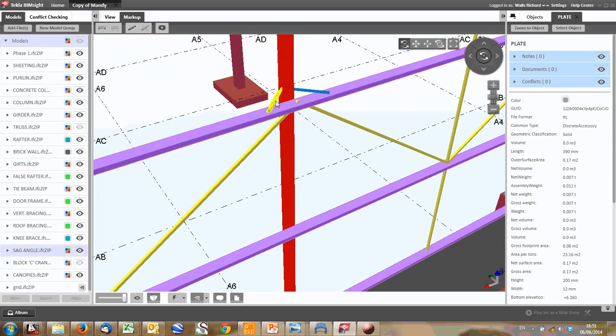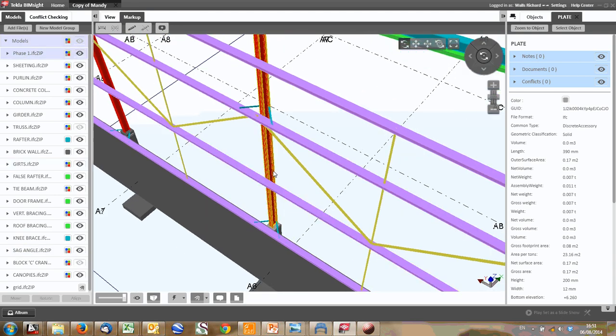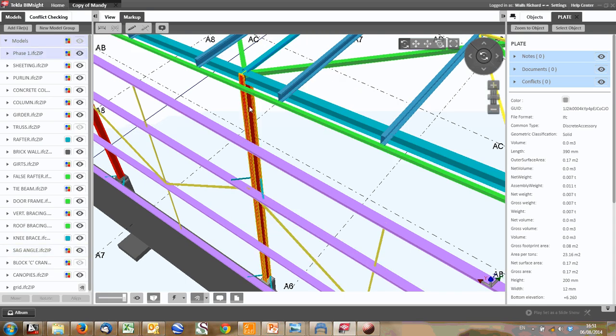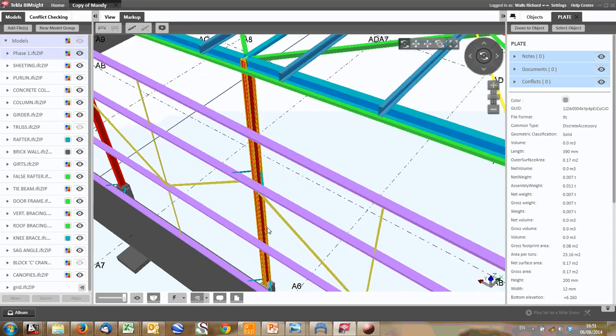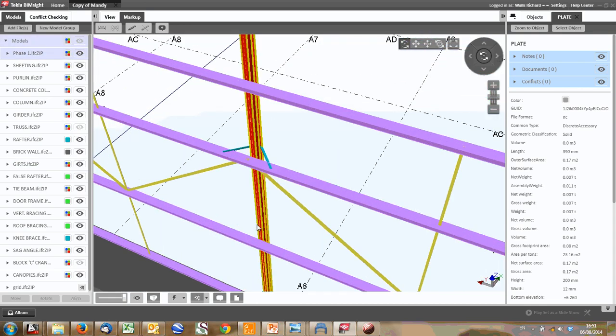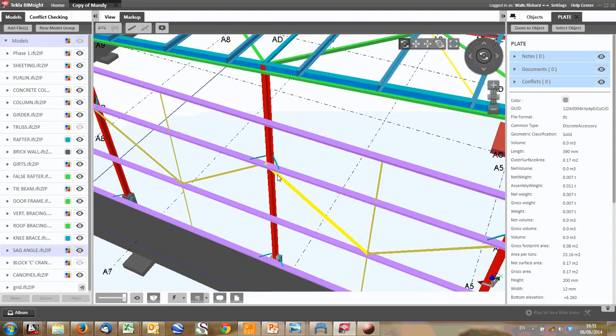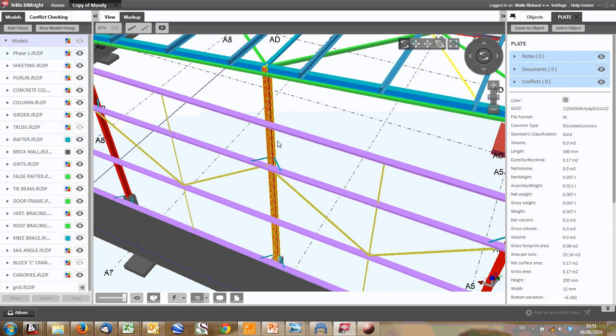When you're designing it, you use these knee braces to stabilize it, so that shortens the effective length of the back column. From the knee brace to the bottom, or from the knee brace to the top, or if there are multiple knee braces, from knee brace to knee brace. If the front flange is going into compression and it wants to buckle, it's supported from girt to girt, because these girts support it, but the back flange is unsupported. Alright, we've analyzed our column now, and one thing though, with these sorts of steel members, they're normally governed by deflection.